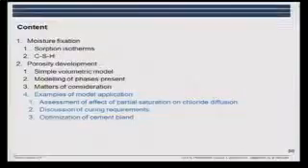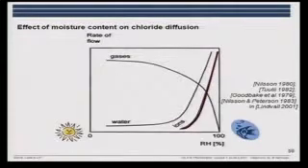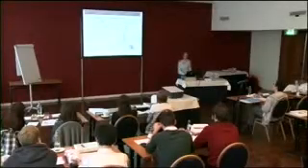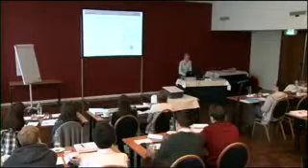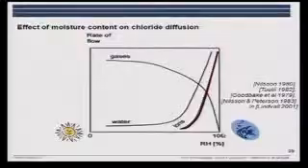One thing you could say, when we have a structure, is first of all the impact of moisture on the various transport mechanisms. Here you have the rate of the flow as a function of the relative humidity. If we have gases, they will be transported most easily if we have a dry material.